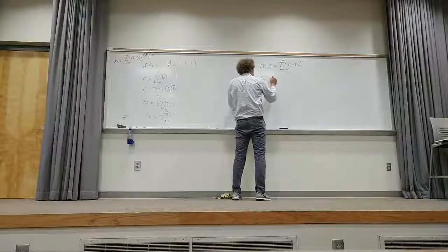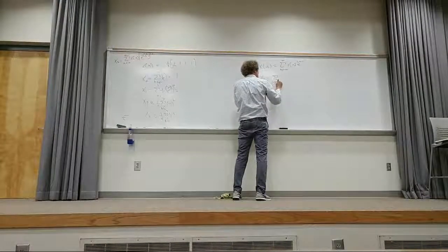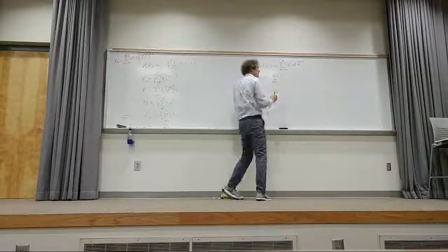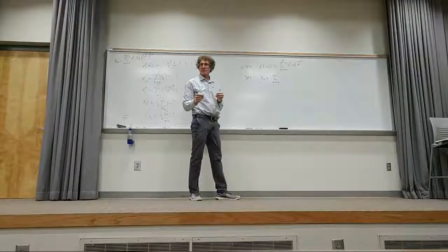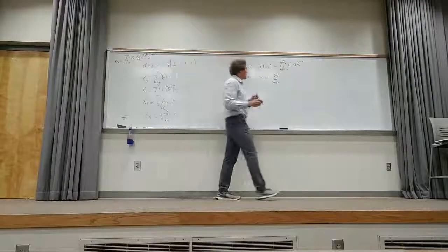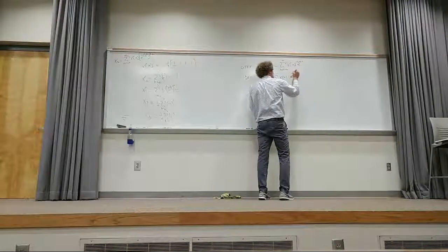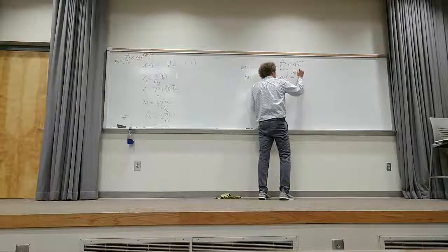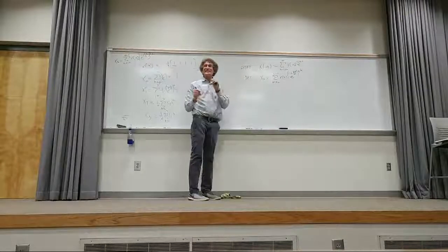X of k here is a summation. Now the range goes from n equals 0 to N minus 1, where capital N is the number of samples, right, people? Please watch this. Agreed? It's still times x of n, right? But now this becomes e to the minus j, 2 pi over N, times nk power. Now I want you to look at this carefully.